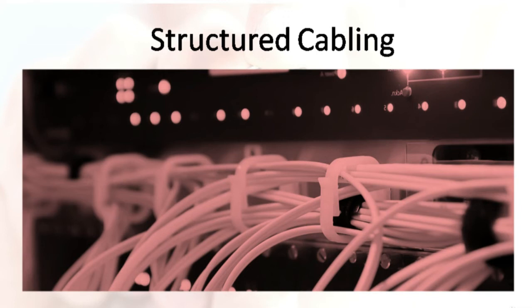If it is buried underground without ducts to protect it, then you will need to specify outdoor cables with armoring, such as external galvanized steel wire and or corrugated steel tape. The other major component is the connecting hardware, where the most common ones are either 8-pin modular connector plugs and sockets, and the other type is the insulation displacement connectors, also known as the IDCs.